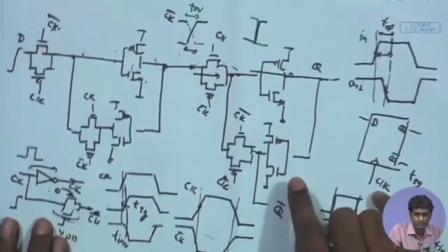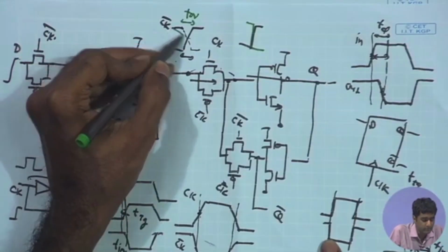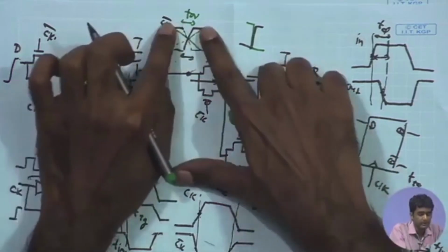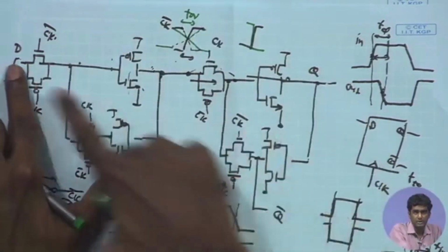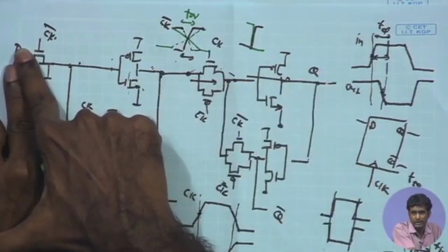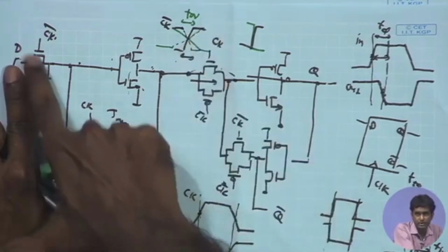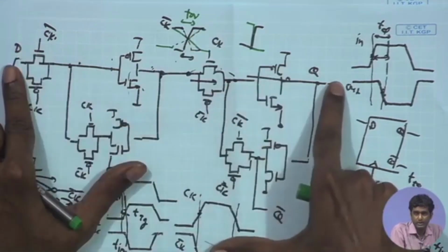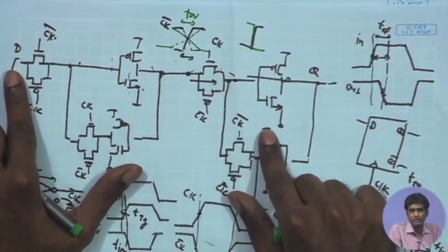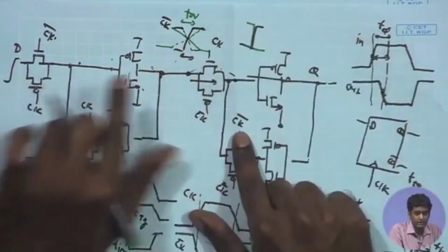So, if you are having a larger overlap between the rise and fall time, if the waveforms are much more sluggish, then you are having a longer duration for which the output is directly transparent to the input, and during that point, despite the transition happening at the positive edge, you can have the data from D propagating to the Q, and therefore you can end up latching the wrong data.